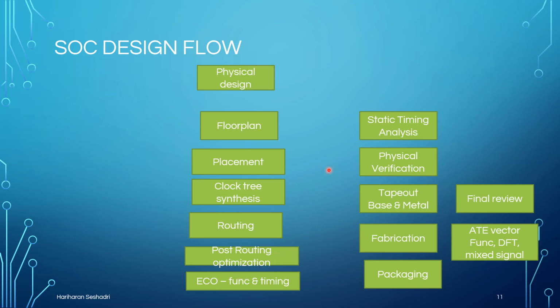There's something called static timing analysis, an extremely important topic. STA, what we call STA, static timing analysis. You should know what is the setup time, what is the hold time, what is the removal time, recovery time, and everything. You should know all those things. Then you could do the static timing analysis. That is a separate topic, outside the scope. You check whether the design will work or not.